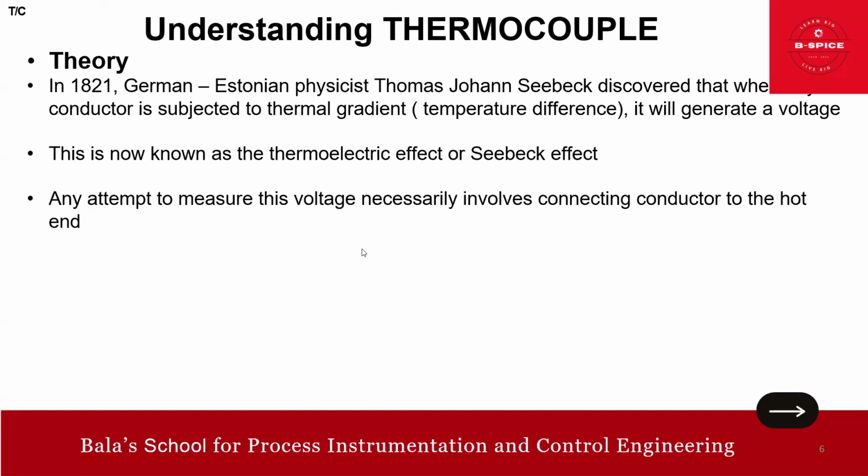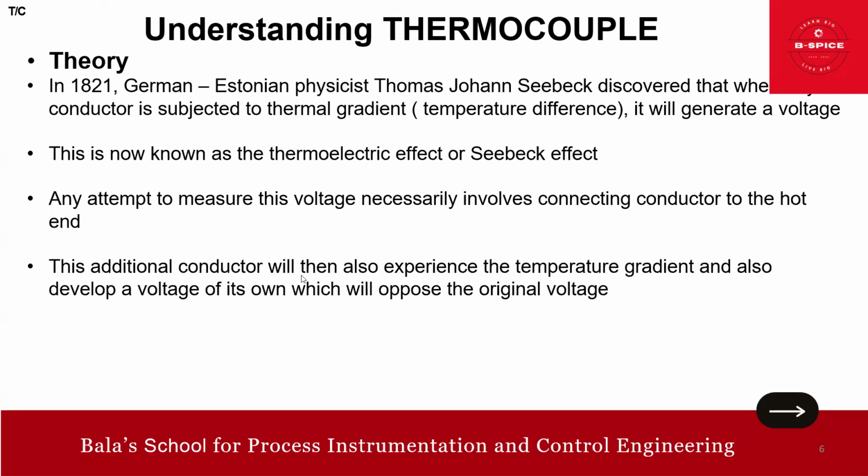So here, one thing I want to also tell you, friends: any attempt to measure this voltage necessarily involves connecting a conductor to a hot end, right? So you need to measure a voltage. This additional conductor also experiences a temperature gradient, meaning a temperature difference, and also develops a voltage on its own, which will oppose the original voltage.